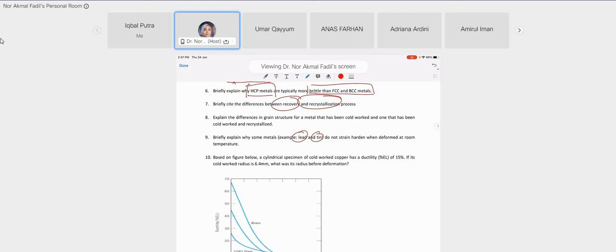If today you do some working process, and several days later there is some increase in the strength of these particular materials, especially pure lead and pure tin, within several hours, maybe several days, it will reverse back to the original properties.